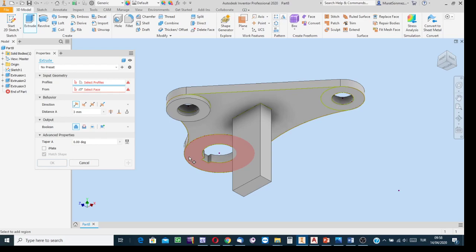In AutoCAD, a sketch can be used only one time, but here in Inventor, it can be used n times. Indicate this profile. For material adding purpose, apply this process. If the direction is correct, then write the thickness. It is 6 with respect to the plane in which we have the sketch. Then apply. At the back side, am I true?